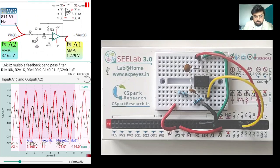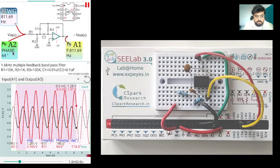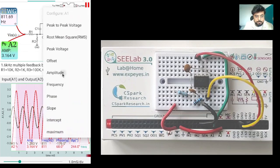If you want to get these values, you simply select a region in the graph. This performs a sine fitting routine on both these graphs and sends the data across to these two labels here, which show you what the amplitude is. You can also look at other parameters by clicking here, and you can see phase differences and other things. Right now we're only interested in the amplitude, so let's just select amplitude for both of them.